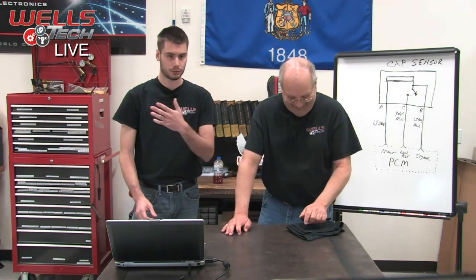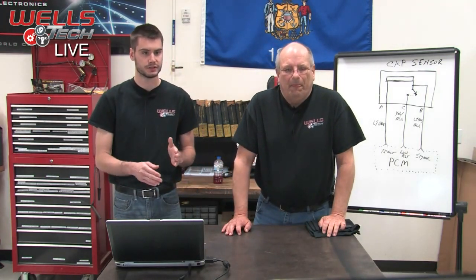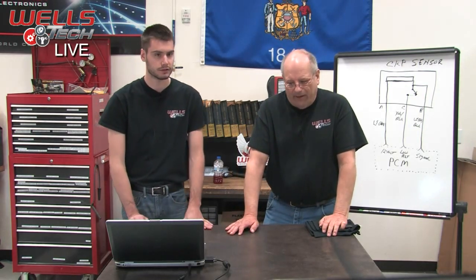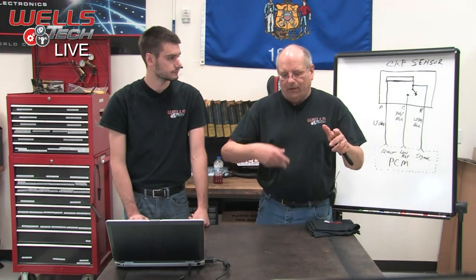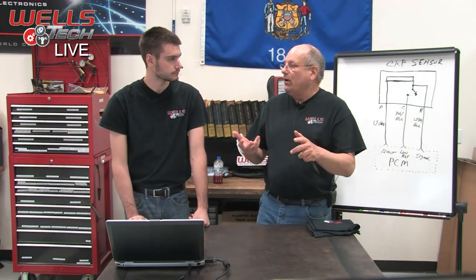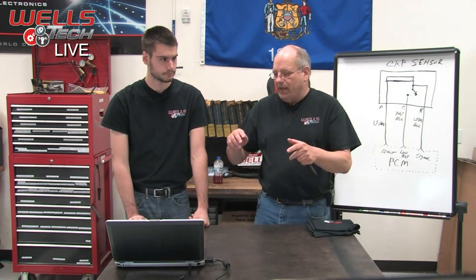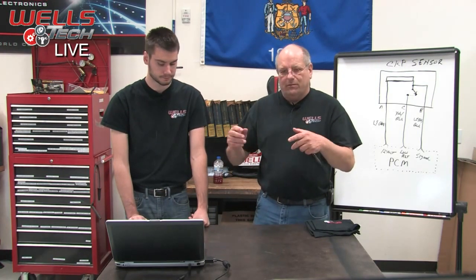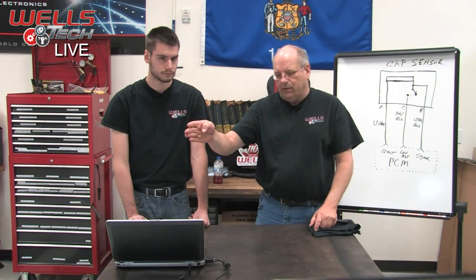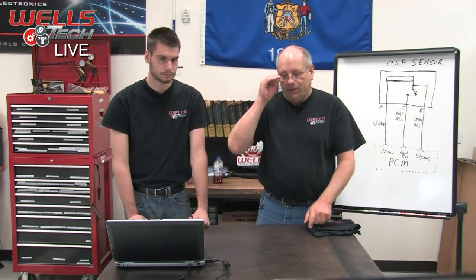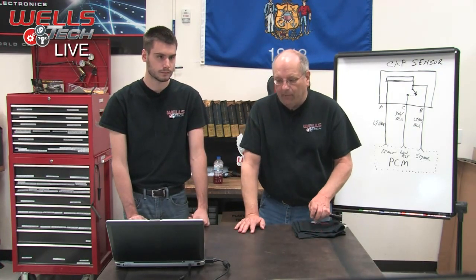When we scope it, and we'll show you guys in a little bit here, you'll see that the signal lasts a lot longer. That signal should go for one full cycle of the crankshaft, because on the camshaft, you just got one trigger. That's all it is. Trigger on, boom, trigger off. And it's the whole rotation of the crankshaft. You'll see on a good pattern here coming up.